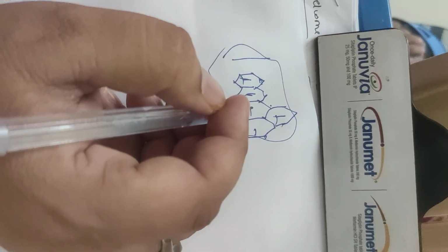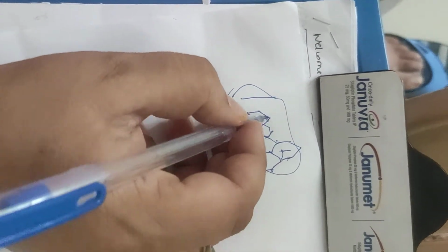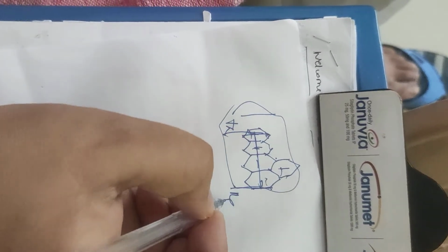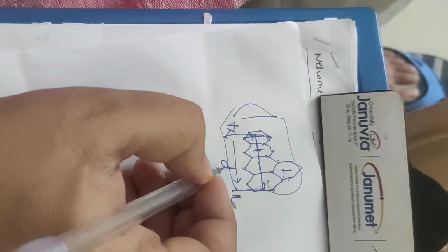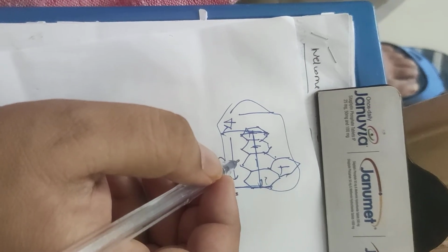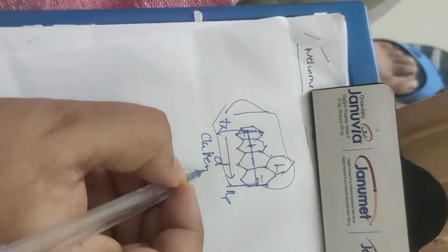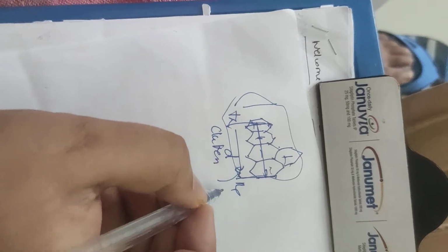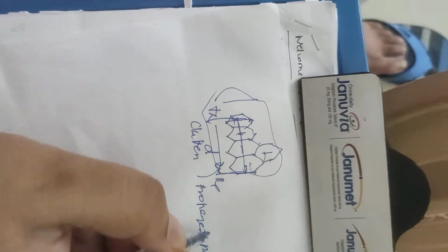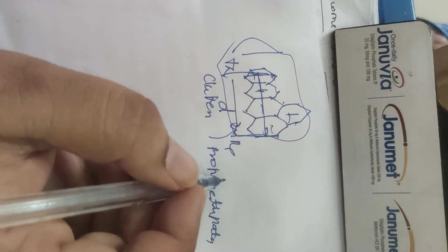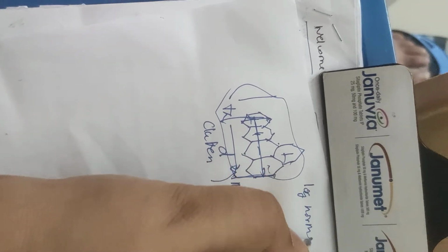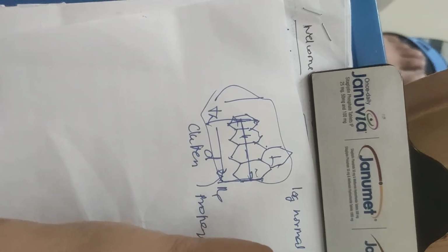So if we transmit, keeping the transmitter and receiver at the same separation distance d, but we have different levels of clutter on the propagation path, then this phenomenon is referred to as log normal shadowing.